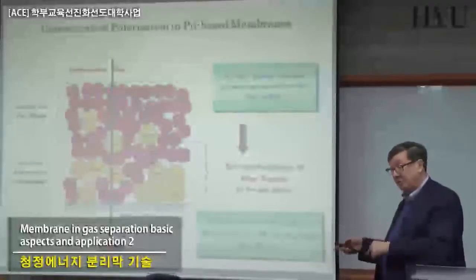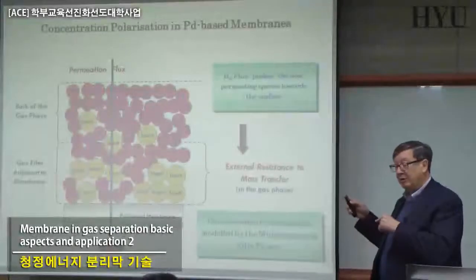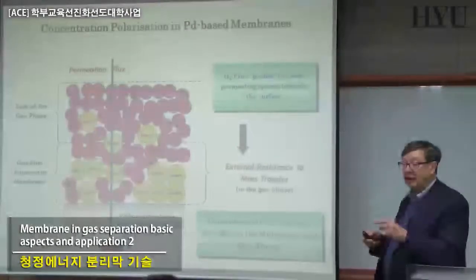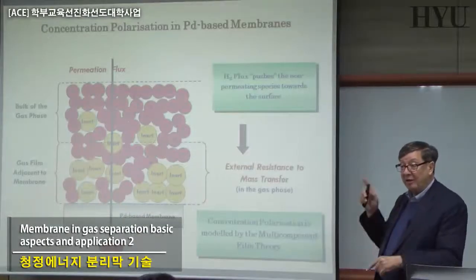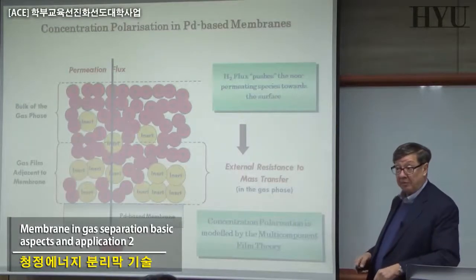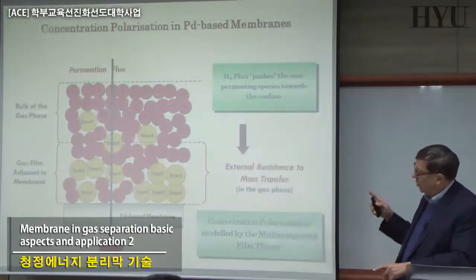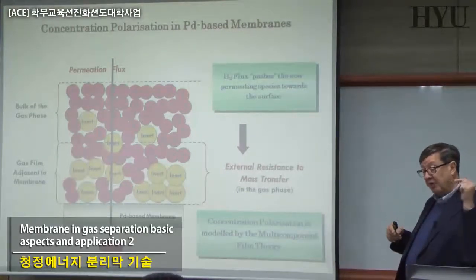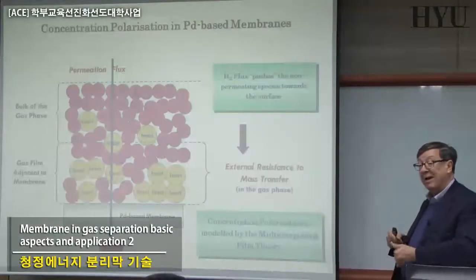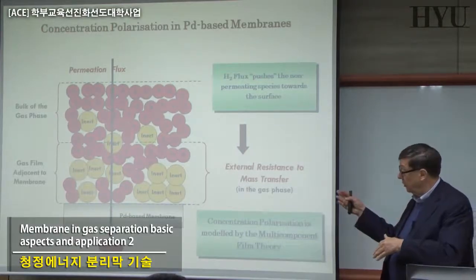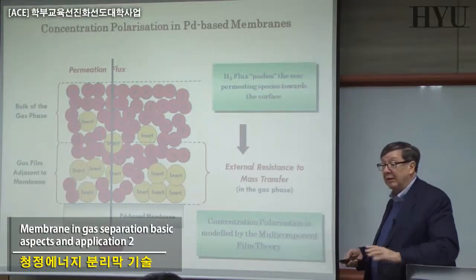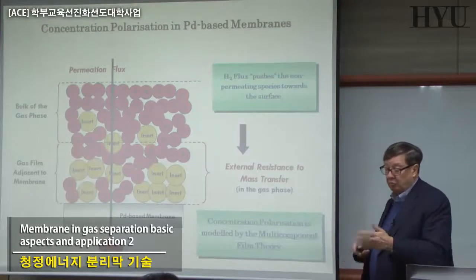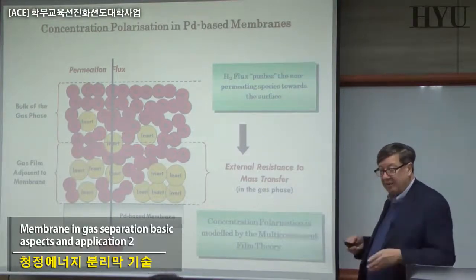Not because the membrane is broken, but because the membrane for that rejection is working against a concentration much higher than the feed. A concentration profile has been created. The origin of this phenomenon is in the difference between convective flux to the membrane surface and back diffusion. Because if what does not go through the membrane is fast in back diffusion, the profile will be flat.